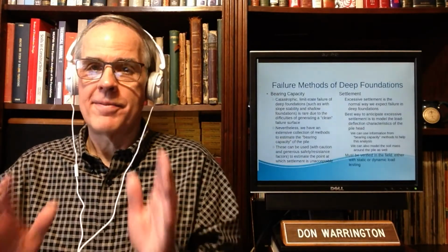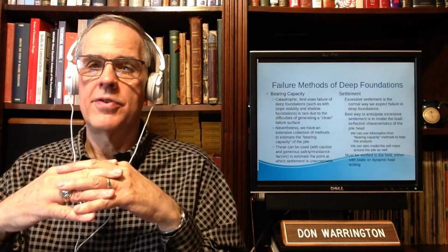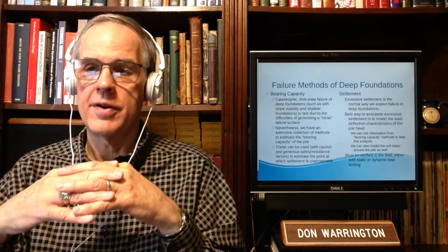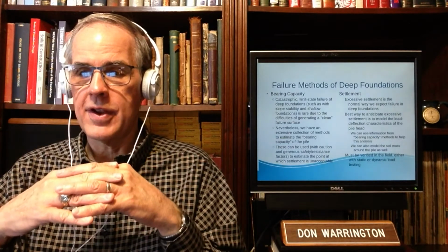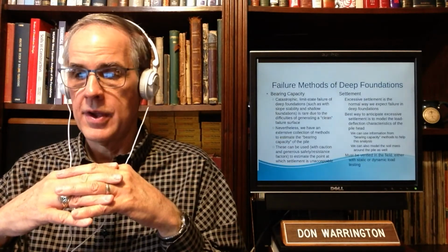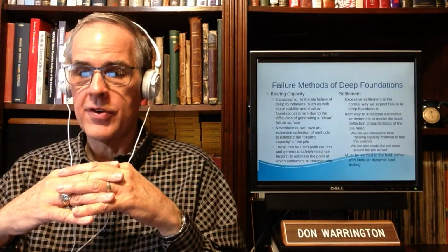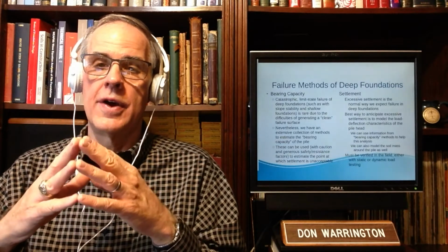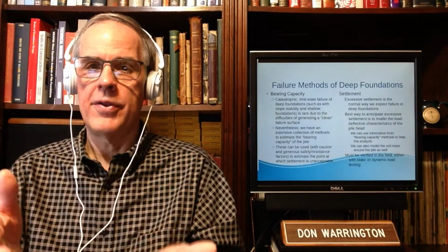The basic bottom line, except in very rare cases where you've got some very soft soils, very high loads, or whatever, is that catastrophic limit state failure of deep foundations, and this is true both with driven piles and drilled shafts, is rare due to the difficulties in generating a clean failure surface. And this has been argued principally around the pile toe, the end of the pile.